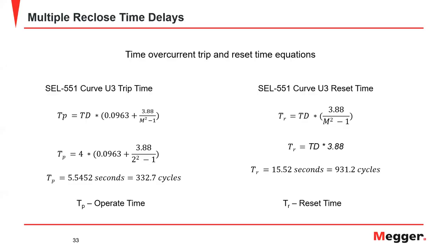There are actually 4 states of matter, but most people think there's 3, and the 4th state is called plasma. When you strike an arc, the extreme heat and the power that goes through it cause atomic changes to take place in the particles. Those particles begin to turn into plasma, which is one way of saying ionized. Ionized and plasma are very similar. So these particles are now conductive.